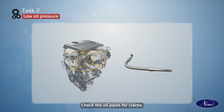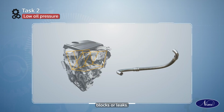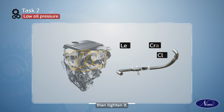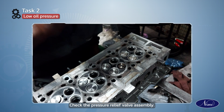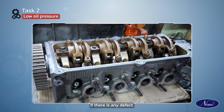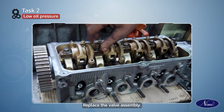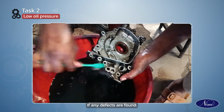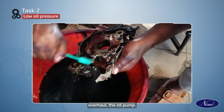Check the oil pipes for cracks, blocks or leaks. If you find any crack, replace it. If you find any block, clean it. If you find anything loose, then tighten it. Check the pressure relief valve assembly. If there is any defect, replace the valve assembly. Check the oil pump. If any defects are found, overhaul the oil pump.